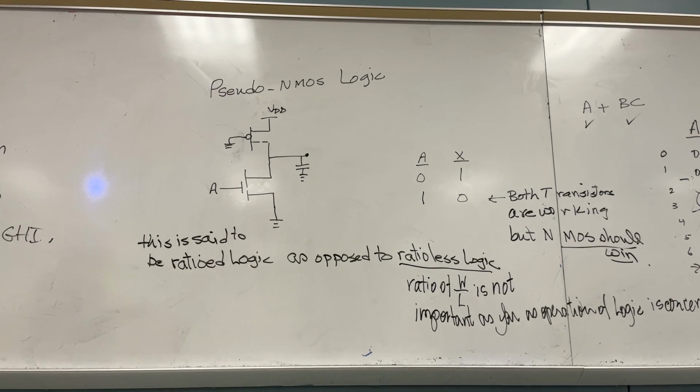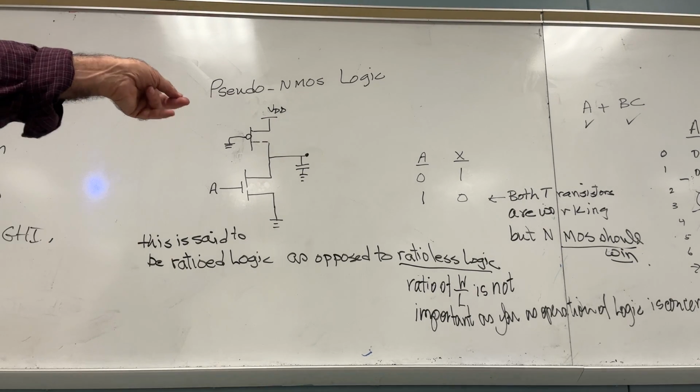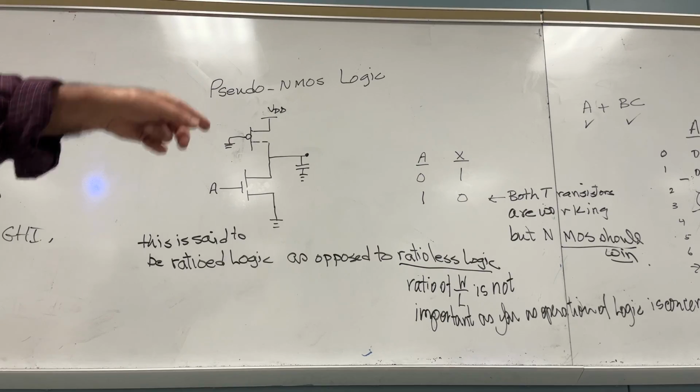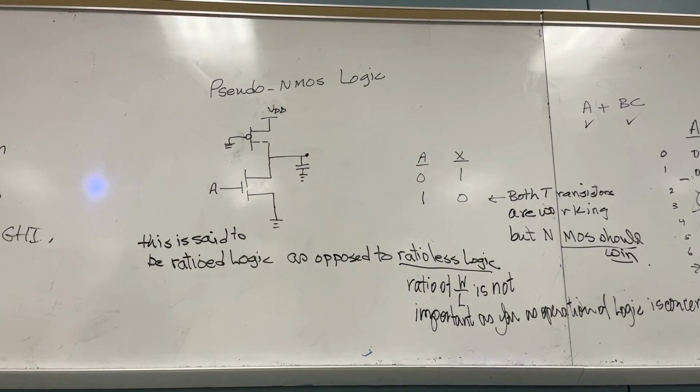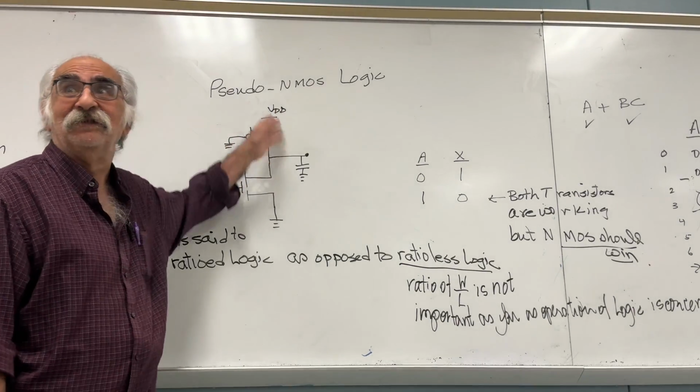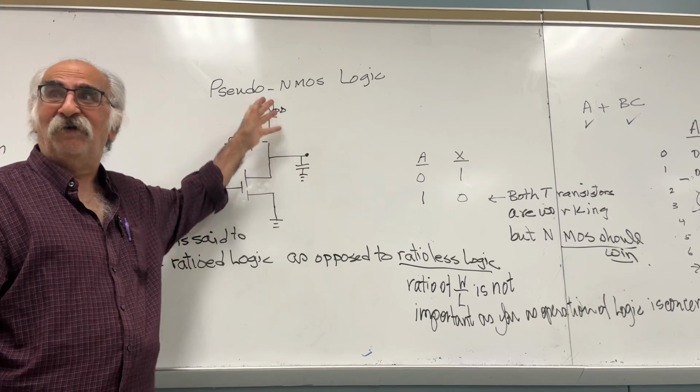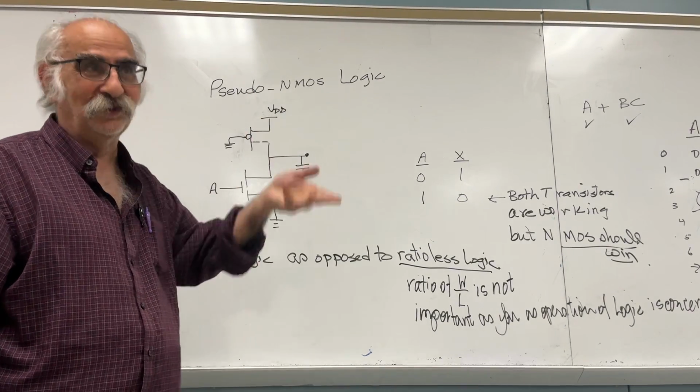Question, someone? Yeah. So the bigger the NMOS, the lower the VOL. That is correct. By the way, the VOL is not going to reach 0. You follow me or not? Because this one is trying again to pull it a little bit up, and this one is trying to pull down. It does not reach 0.